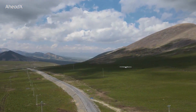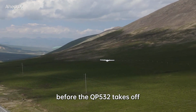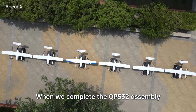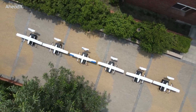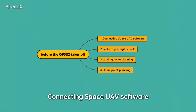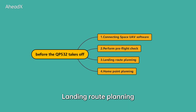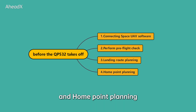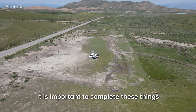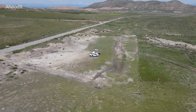In this video, we will show you what we need to do before the QP532 takes off. When we complete the QP532 assembly, we have 4 steps operations to do. Connecting Space UAV software. Perform pre-flight check. Landing route planning. And home point planning. It is important to complete these things before each flight for safe operations.